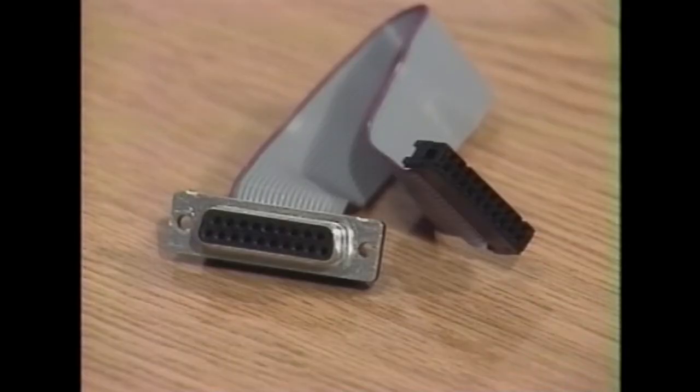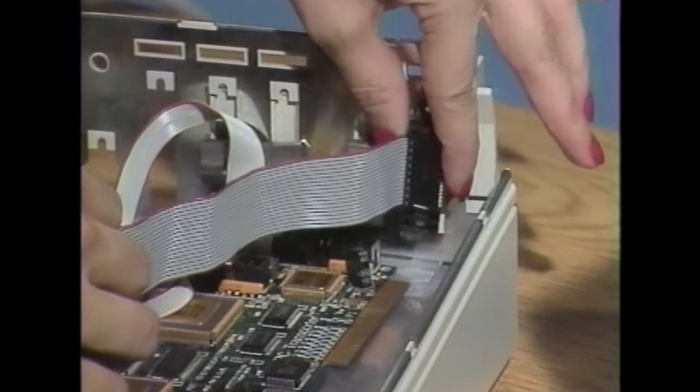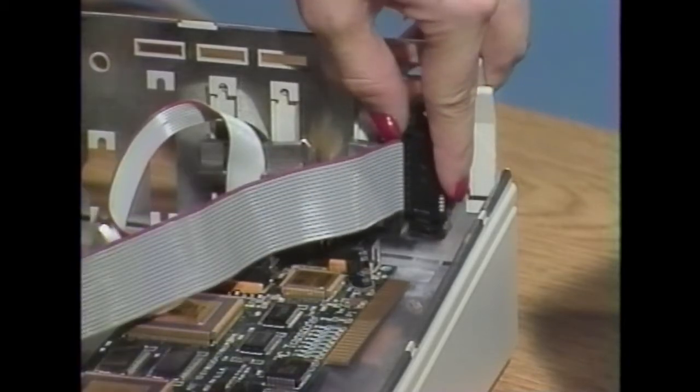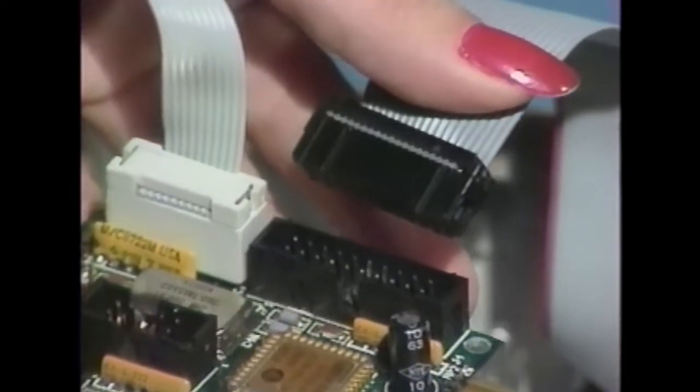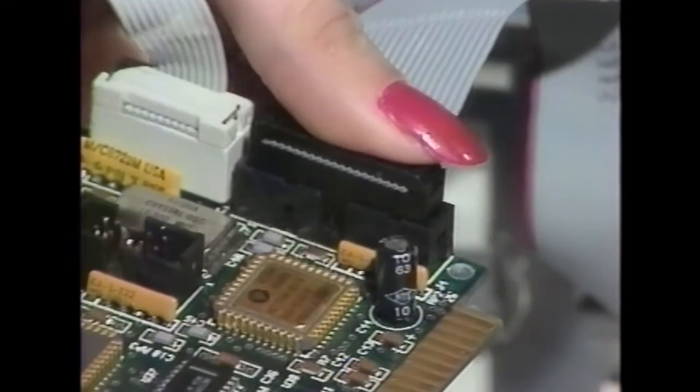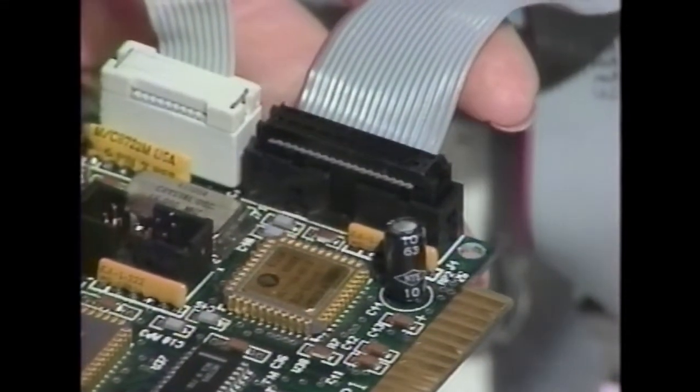Now connect the disk drive cable. It is a 19-wire ribbon cable with a female 20-pin flat cable connector on one end and a female 19-pin connector on the other. Locate an unused medium-sized opening toward the right edge of the backplane. Hold the connector up to the opening from inside the computer while using the included screws to mount it firmly to the backplane. The edge of the cable with the stripe should be the top edge. Now attach the female 20-pin connector to the male 20-pin connector on the transporter as shown.